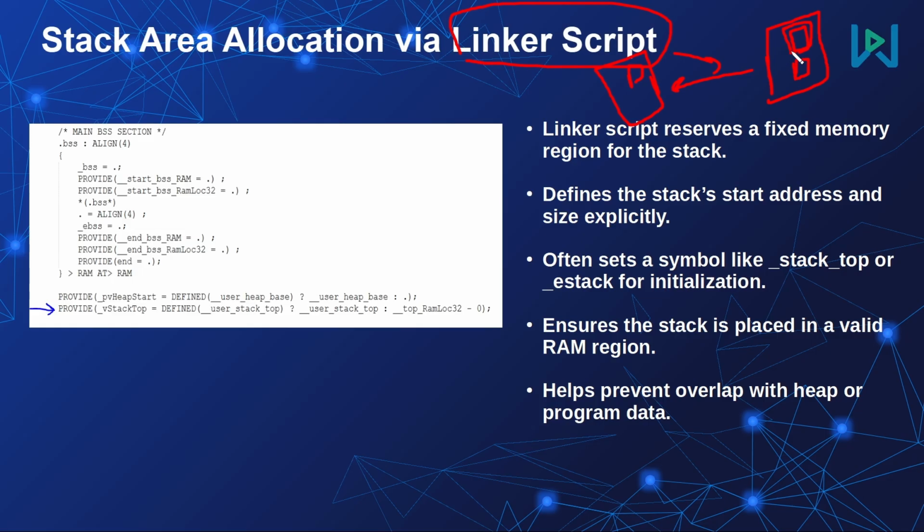In other words, the linker script is the place where we are going to initialize and allocate the different sections and memory segments to the supported hardware memory regions.